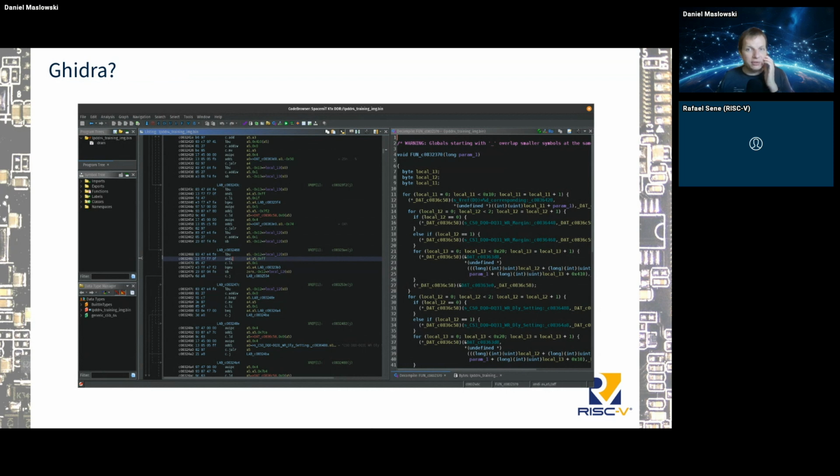What I have done for the SoftGo SoCs was I have just written some small code that would just start reading from the memory address where the mask ROM starts. I was printing out the bytes ASCII encoded, like each byte would be 2 digits in hex code, right? So I just printed that out, put that in a file again, and transformed it back to its binary form. And I actually put a tool for that on GitHub. You will find that in the platform system interface organization on GitHub.